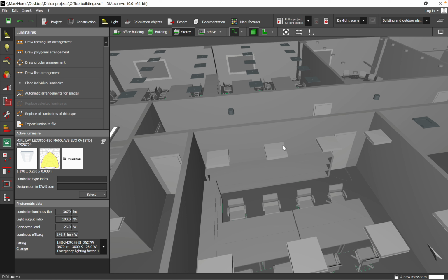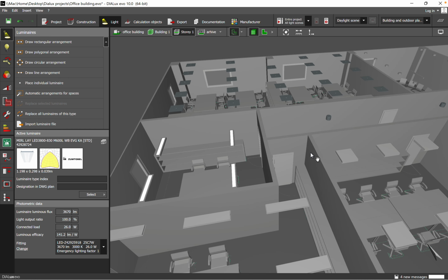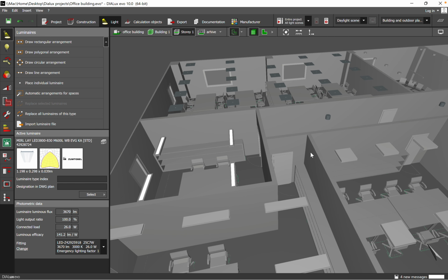But indirect lighting is not really friendly from the point of view of energy saving, because you need a lot of lumen output just to achieve 500 lux with a totally indirect lighting solution. That's a lot of fixtures. So as I said, I'm not really a fan of the solution. But moving on, I would say I move to a mix solution.